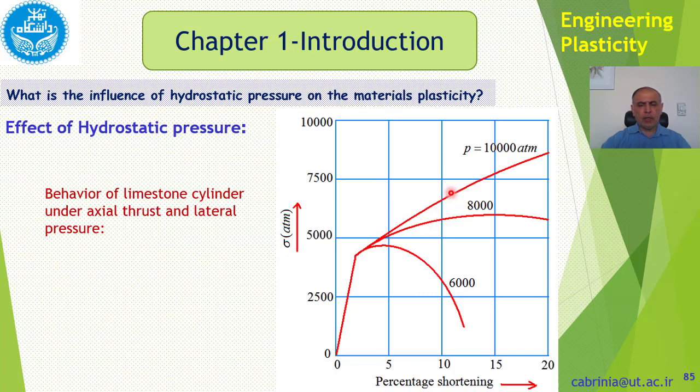Okay, so because the compression or pressure hinders the growth of a crack, that's why the material behaves like this. Okay, it doesn't let the crack grow, and so there is no break, no failure under high pressures. So sometimes if we form a material like titanium and we see a lot of cracks in it, if we form this material under high pressures, we won't see those cracks.